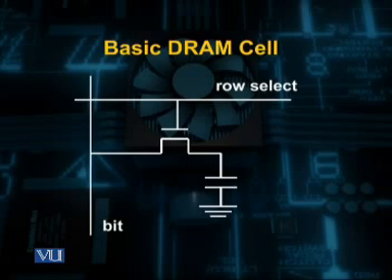However, as the information is stored in a capacitor and practically the capacitor may get discharged with time, the value once stored in this capacitor must be refreshed after regular intervals of time, which may range from tens to hundreds of milliseconds.